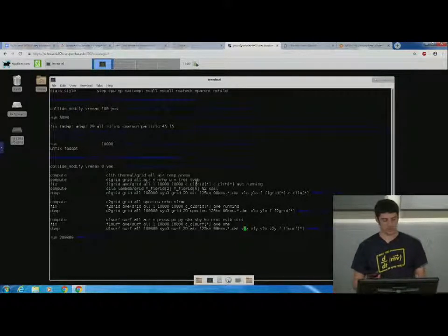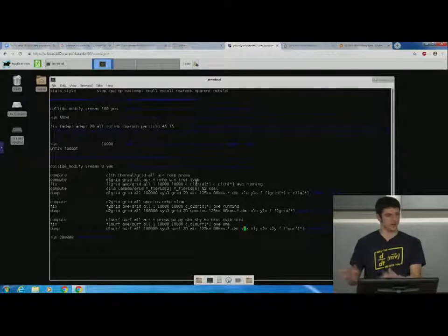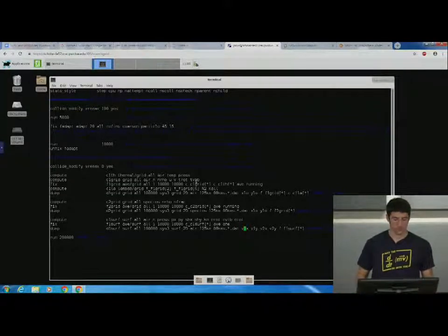The way SPARTA breaks it up is for 2D surfaces, I have 2 coordinates, to start. Every part of the surface is a line, right? So it breaks it up into panels. So I have basically my XY coordinates of one point and my XY coordinate of the other point of the surface. For a 3D problem, it forms triangles. So you actually have 3 coordinates for each point, and you have 3 of those points. And then we'd have v1x, v1y, v1z, v2x, v2y, and so on, so we have a total of 9 points here.